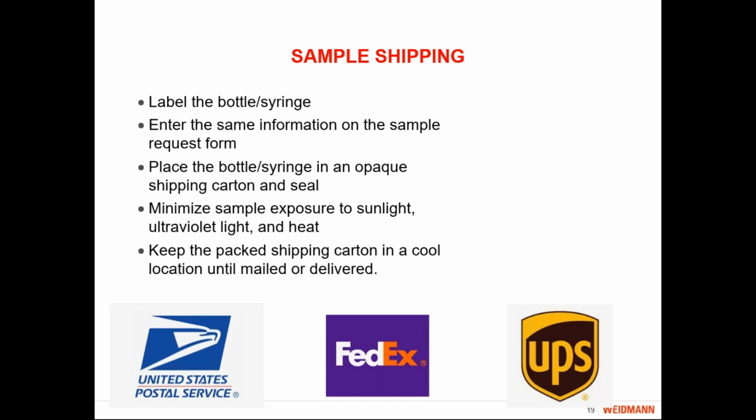Don't take your bottle and your syringe and set it on the dashboard of your truck while you go off to lunch or go take some more samples. Don't let it sit in the sunlight. That will cause that oil to start breaking down. You want to keep it cool for the same reason. So put it in an opaque container and seal it up.